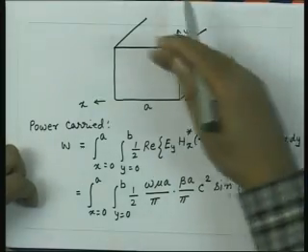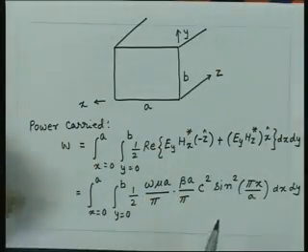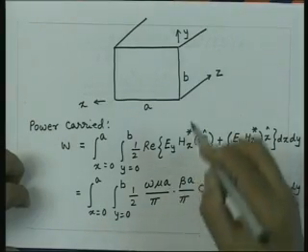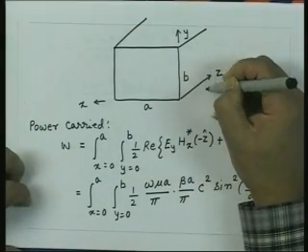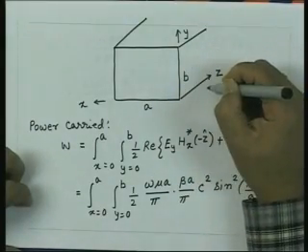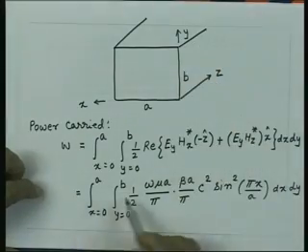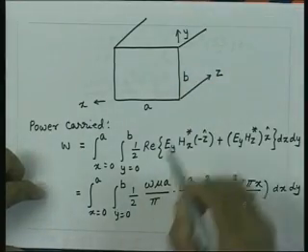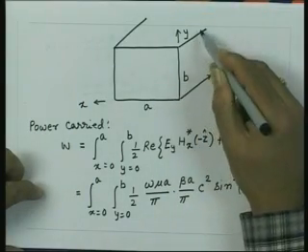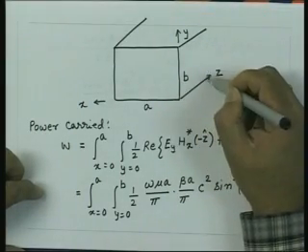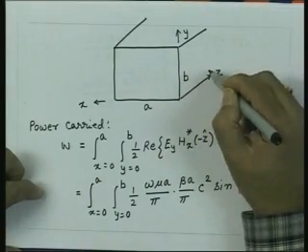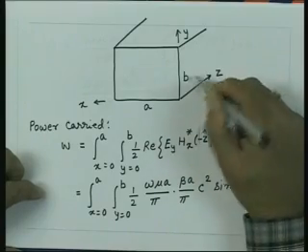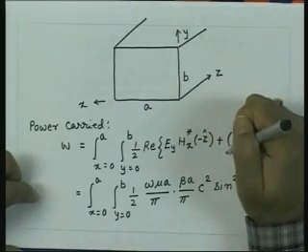Last time we had shown that it has more like some kind of a flower pattern. So on this wall the current is constant, because the component of the magnetic field, which is Hz, does not vary as a function of y. So on this wall we essentially have the current which is oriented in this direction and it does not vary as a function of y.